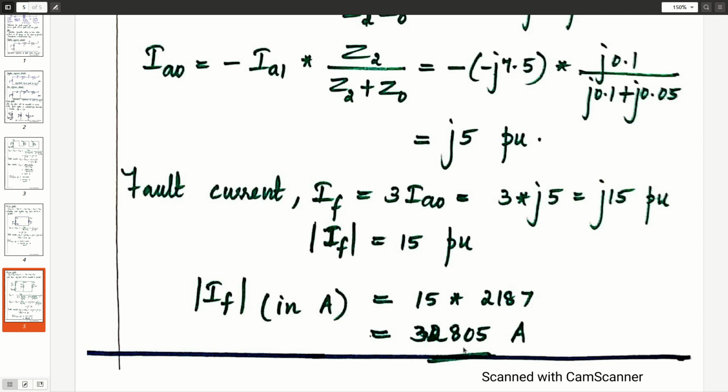So in Thevenin's equivalent positive sequence network, we have VPF in series with Thevenin's equivalent positive sequence impedance. So this VPF and Thevenin's equivalent positive sequence impedance are calculated with respect to the fault point and the reference.